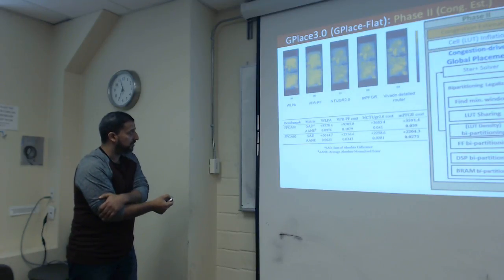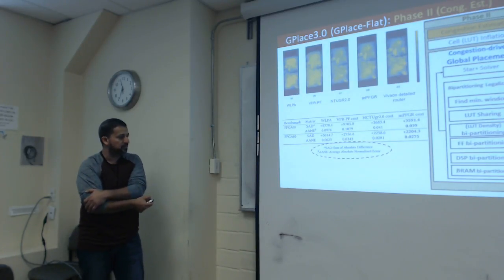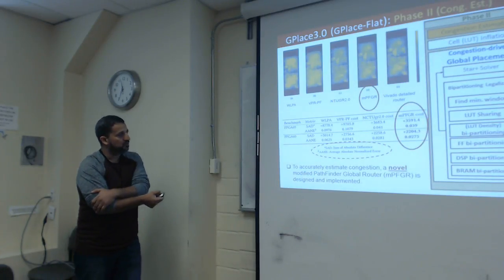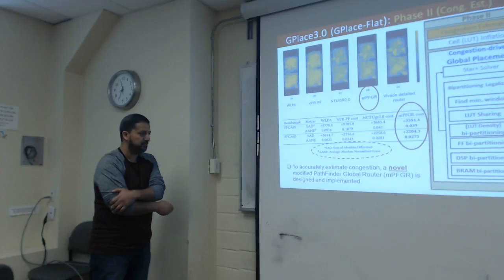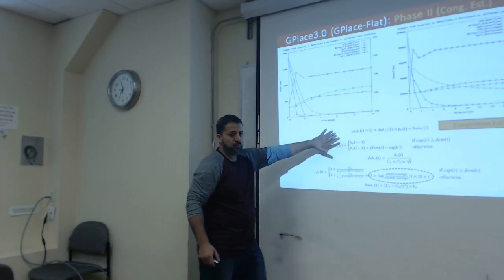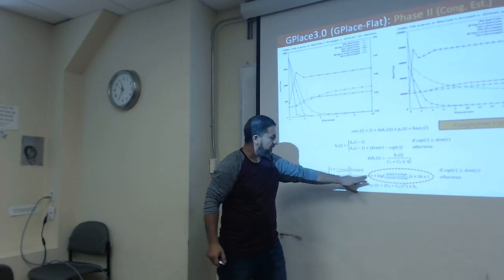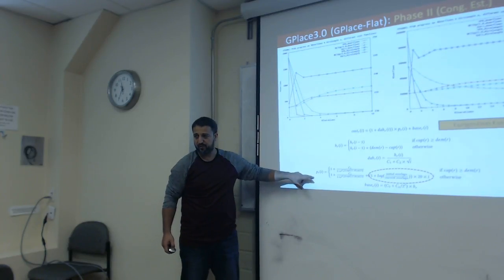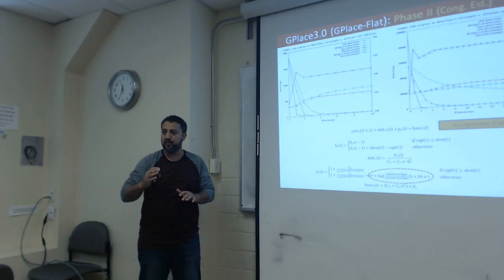Based on this figure, as well as the table that shows some similarity metrics, we found that this is the closest to the true detailed router congestion heat map. This shows the equations used for the ASIC global router. The only thing we modify is that we adaptively modify the present cost, and that's not adaptive by time, but adaptive by the progress of the global router.